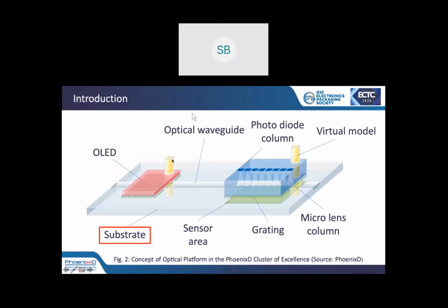The surface quality of the waveguide material is, as expected, better than the PEEK substrate and can be used for the waveguides and optical signal transferring. A very interesting part was the grating structures, which could be manufactured on the steel inlay and could be transferred into the composite polymer material, even though particles of up to 5 micrometer diameters are inside the polymer matrix of the PEEK substrate.